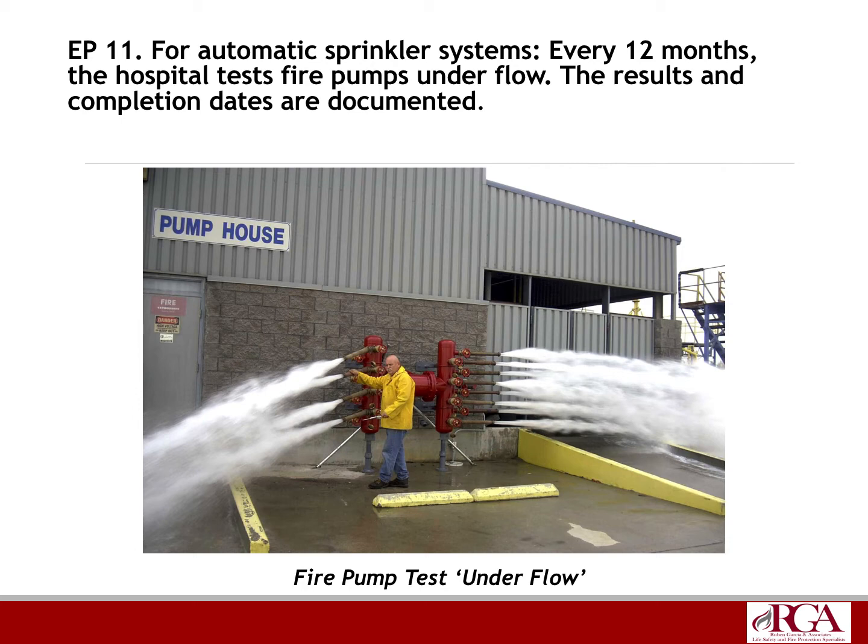And when they do the 150% capacity test, make sure they're doing it under emergency power, that is, the emergency generator. Make sure that's documented. Surveyors will look for that, and that's low-hanging fruit when they go to look at this specific EP11.